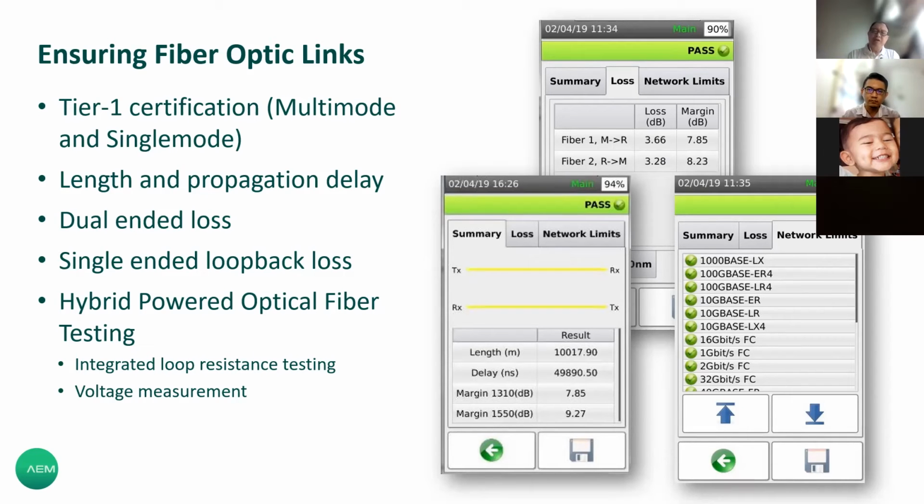So when we measure fiber, for our application, for our industry, I'm talking about the structured cabling industry, our fiber can no longer go more than 1 kilometer. It is very uncommon. Why? Because of application. The IEEE came up with applications like 10 gig, 100 gig, or 1 gig.